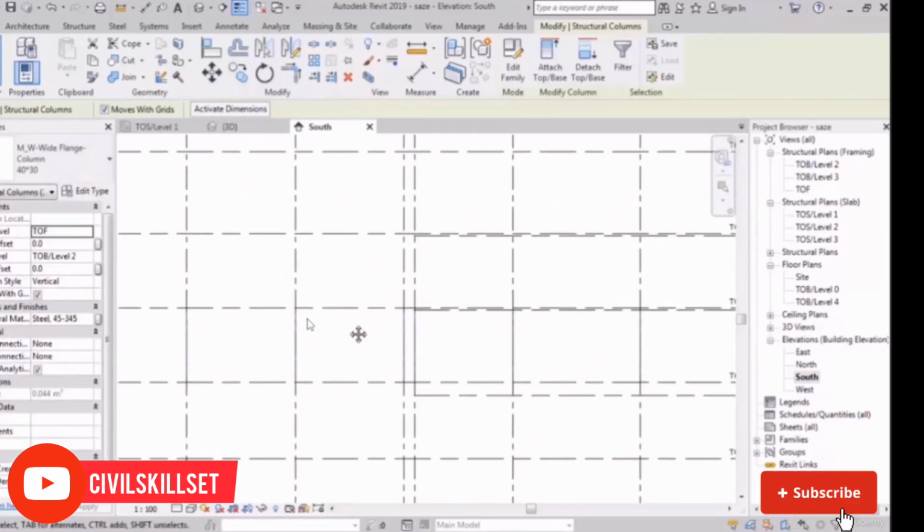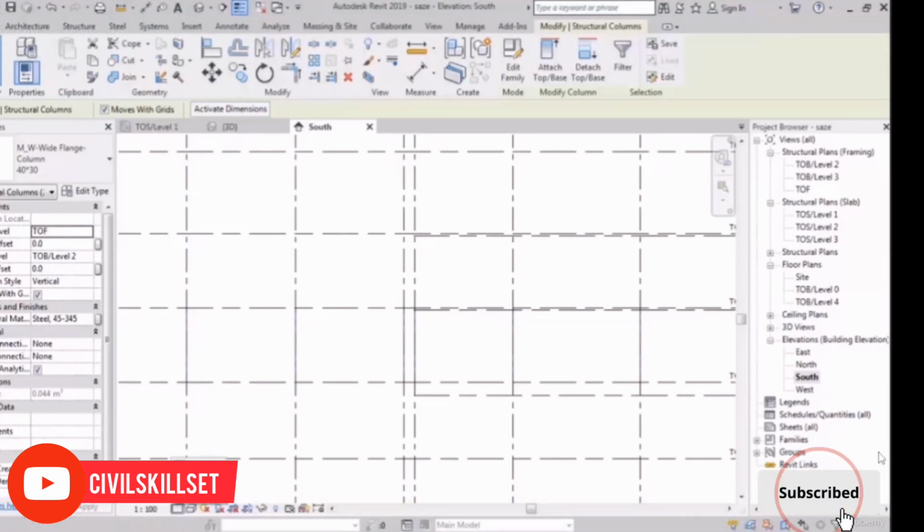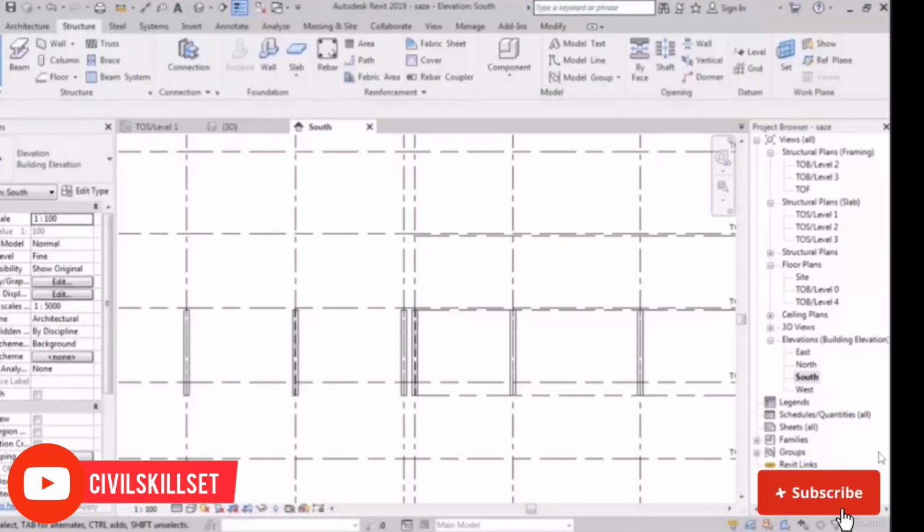Now a question. Why are the columns being seen as lines? Why can't we see the thickness, the volume and all that? Can you say what this relates to? Why, instead of showing us the volume of the columns, is it showing us the lines? That's right, it's related to detail level. If you open it and then choose fine, we can see the volume of the columns.